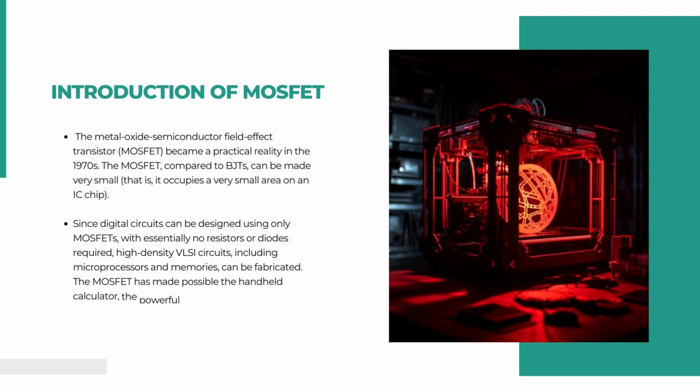The MOSFET compared to BJTs can be made very small, that is, it occupies a very small area in an integrated circuit. Since digital circuits can be designed using only MOSFET with essentially no resistors or diode required, high density VLSI circuit including the microprocessors, memories can be fabricated using the MOSFET.